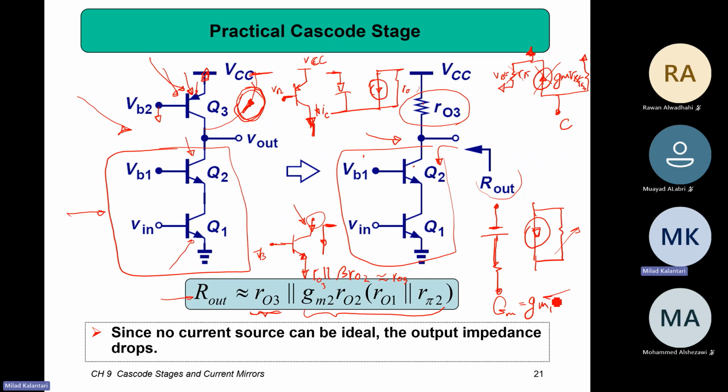The gm is the same as before. The R out for the cascode is the same, but the R out of this current source comes into the equation, right? The reason the gain was not high is that this RO is not high. So you try to increase the gain by increasing the output impedance of this black box, the cascode itself, but you are now limited by the R out of the current source you put in. Is that clear?